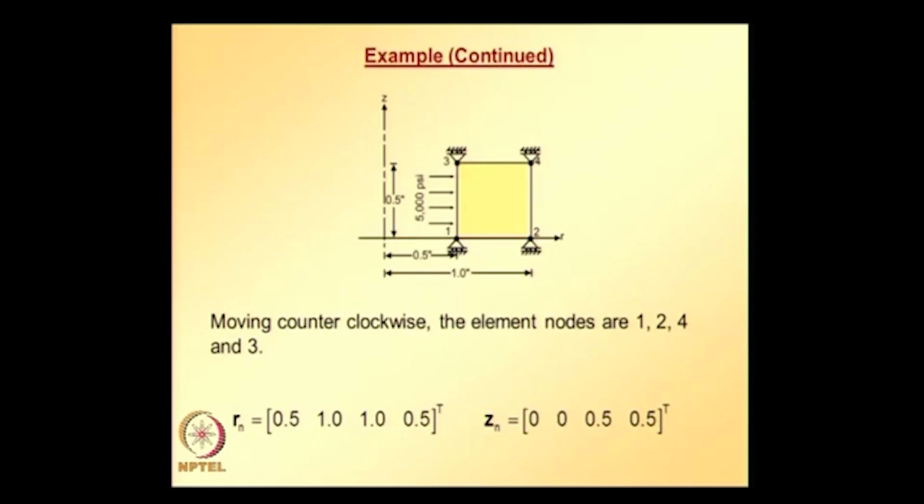and we adopt 2 by 2 Gaussian quadrature, we know how to get the coordinates and weights of each of the integration points. So here we look at the calculation details corresponding to one integration point, and similar operations can be repeated at the other integration points, and contributions from all integration points can be taken to get the final element equation, the final element stiffness.